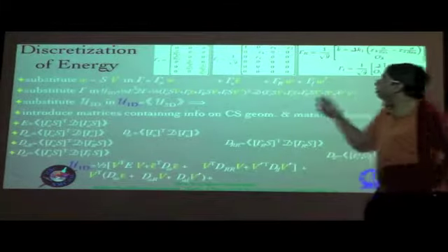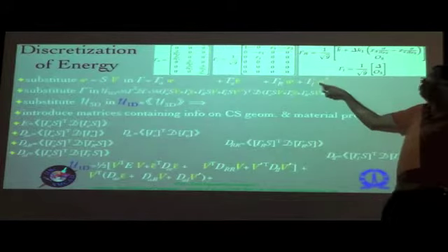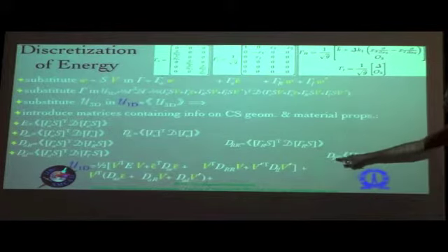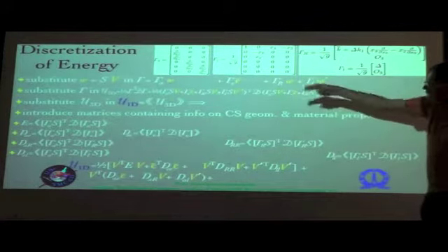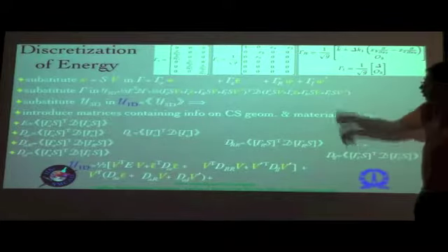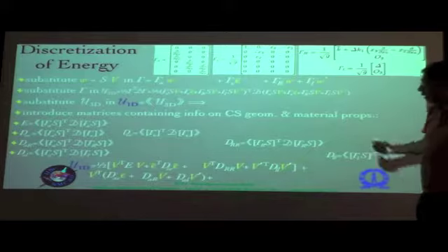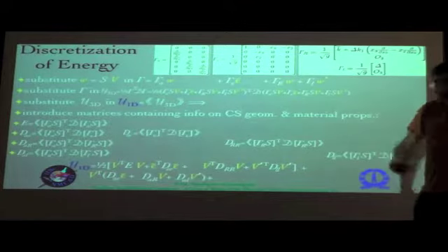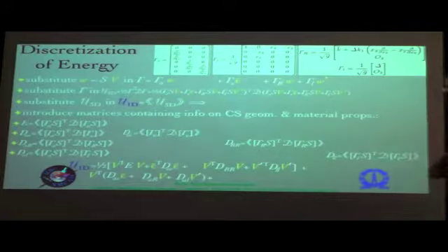It's associated with the primes in the warping, because of the W prime that you have here, and that we call as L. So there are 4 types of subscripts here: A, epsilon, R and L. A associated with the cross-sectional dimension, epsilon associated with the classical strain measures that we have already extracted, R associated with the initial curvatures, and L associated with variations of the warping with respect to the x1 direction.